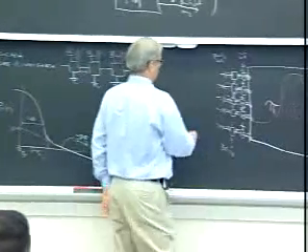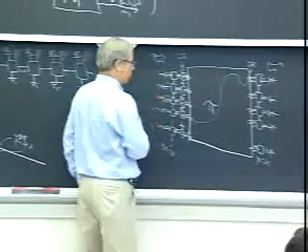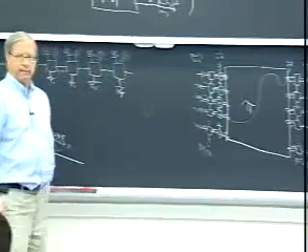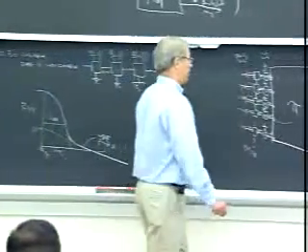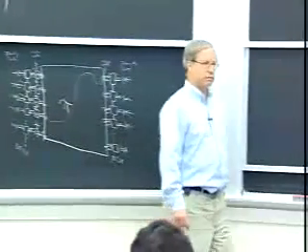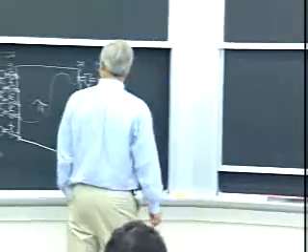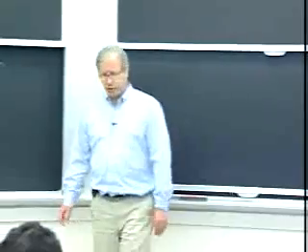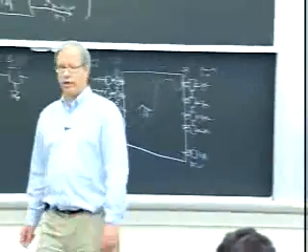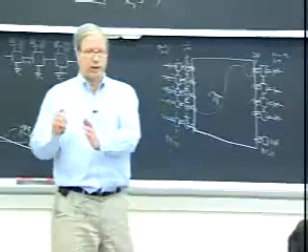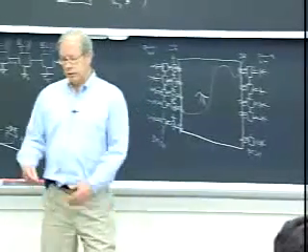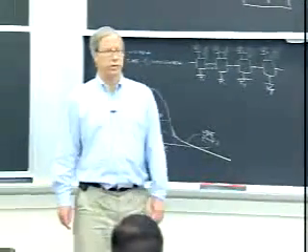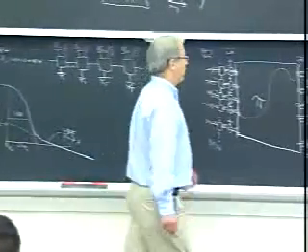Or shortening. Shortening is where you hold some of these bits to 0 and don't send them. Puncturing means you let them go free and don't send them. So I don't know, but I don't think this is a very profitable way to go. But it's certainly a reasonable question to ask anytime that you get into a minimum distance limited situation. You should think about, is there some way I can just expurgate that small fraction of code words in the neighborhood of every code word that have bad minimum distance? Okay.